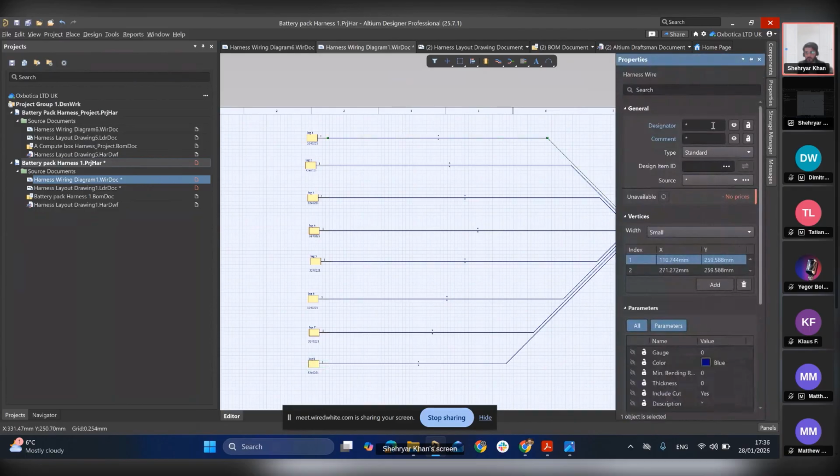wires. So you should name your wires and give the properties to your wires. Like first of all, I should be designating it. This is wire 1, W1 in designator, and in your comments. You should fill these because once you're validating your project, errors will appear in your schematic. So I'll just hide my comment, but I'll leave the designator, which is coming up here on the wire. Similarly, for all the wires, we should be doing it quickly. W2.